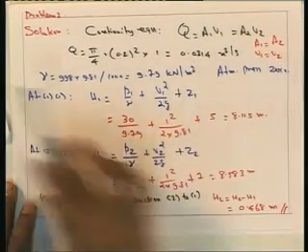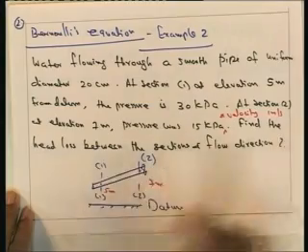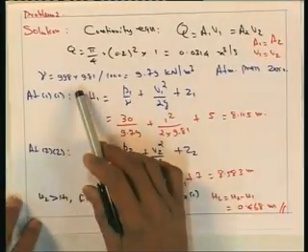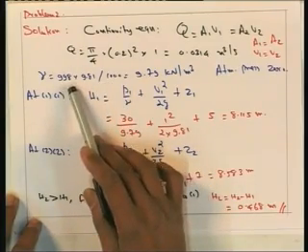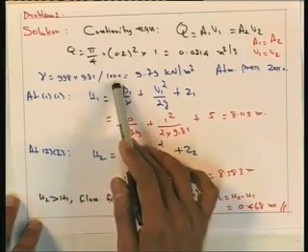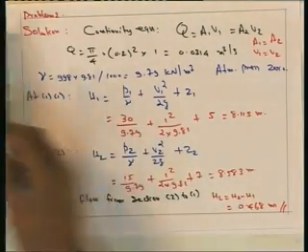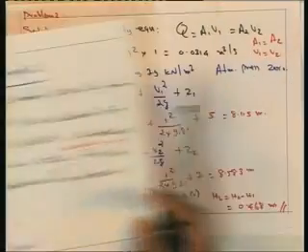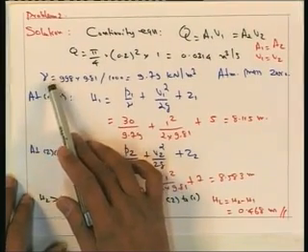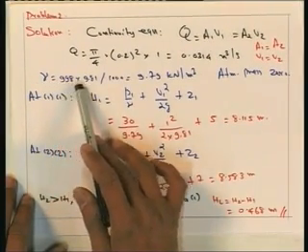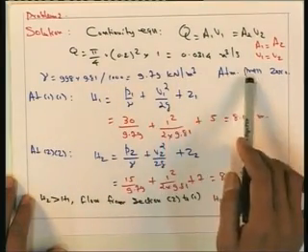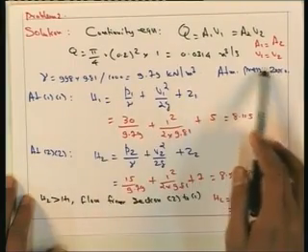Since the pipe is assumed to be of uniform diameter, V1 is equal to V2 and A1 is equal to A2. Also, the density rho is given as 998 kilogram per meter cube, which can be converted: gamma is equal to rho g, so 998 into 9.81 by 1000, which is 9.79 kilonewton per meter cube. We are considering atmospheric pressure, and hence we are taking it as 0.